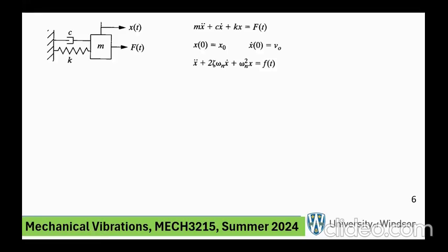Remember, I said that if you give me the value f hat, which is an indication of what the force is during that extremely short period of time, I can multiply that magnitude by the delta t, the time duration, and divide it by the mass of the block, and that will give me the initial velocity of the block. Okay, so because it's an impulsive force,